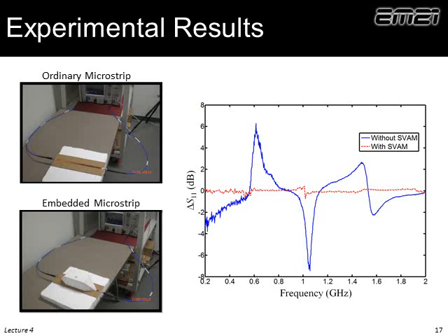So here's our experiment. We took a microstrip transmission line, we hooked it up to our vector network analyzer, and what a vector network analyzer does, sometimes just called a VNA, is it pumps out a signal, and it looks at what gets reflected and what gets transmitted. And so we get transmission and reflection measured by our VNA. So we hooked up a regular transmission line, so we get near 100% transmission at first, and then we put a metal ball up next to that line, and then pull it away, put the metal ball up next to the line, pull it away, and what we see is the reflection and transmission jumps around. And the blue line over to the left is the change in the S11, or the reflection parameter, as we take the ball and put it up against the line and pull it away. So we see almost 7 dB jumps.